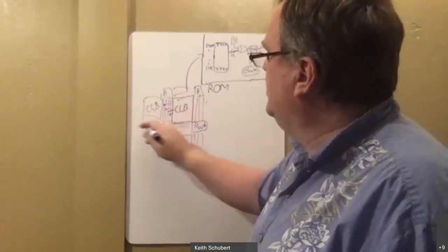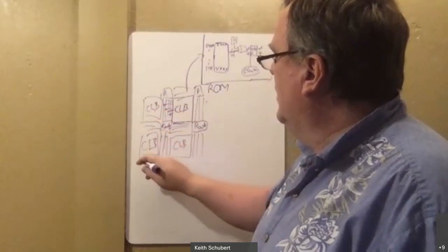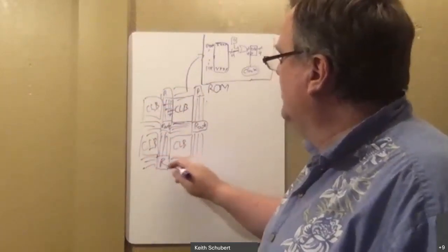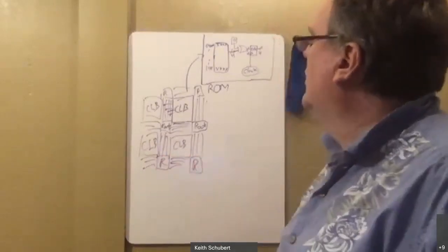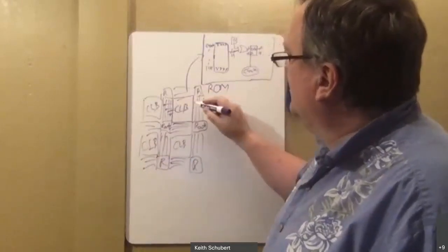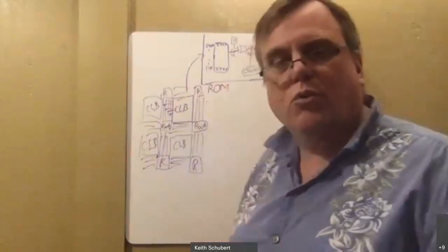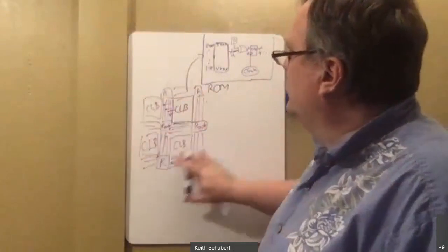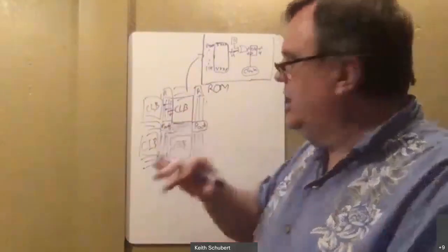They just set up this giant array of these logic blocks connected by routing arrays all the way through. So you end up with this type of a setup, and the inputs come in here and the outputs go here, and you can route the signals however you want to route them. So regular logic signals are all part of this, and this is on one layer on the chip.